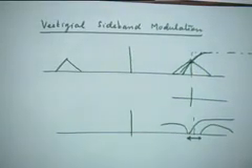However, there are certain kinds of signals which have a lot of low frequency content and which are sensitive to phase distortion. One such set of signals is the picture signal I mentioned to you. So you have picture signals, you have facsimile signals, which are also a kind of picture signal, where you are scanning the content of a page. All these signals are very sensitive to phase distortion, which will occur if you try to implement an SSB modulator.